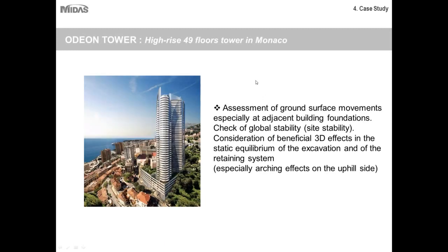Okay, so my last case study is the Odeon Tower, which is a 49-story high-rise building in Monaco. As you can see, it's an assessment of ground surface movements, especially at adjacent buildings. In other words, as they were building the foundation, in this very developed area, in order to perform the excavation and to build a foundation, they first needed to study the effects of this excavation on the nearby structures, just to make sure that the stability and the strength of these foundations wasn't significantly altered or affected. And because this site had some complex asymmetrical geometry, it needed to be done in 3D.